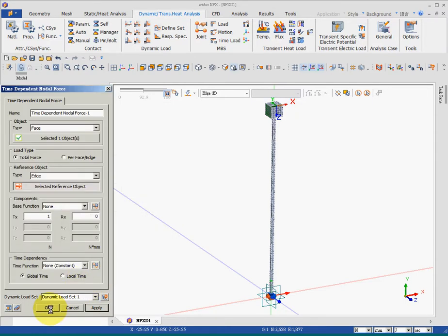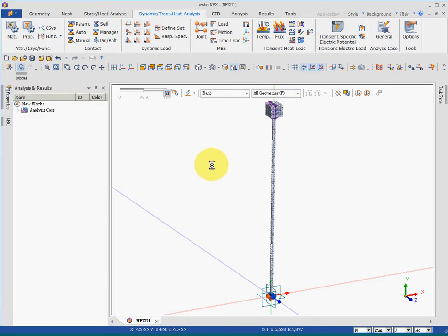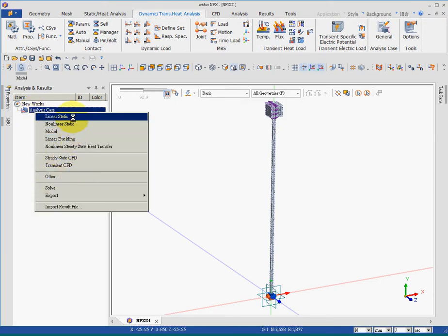So it is called an impact force. So for step 4, we define a constraint and a dynamic force, which include the face or the surface of the load, the direction of the load, and the magnitude of the load, and also a time profile of the load, the impact load.